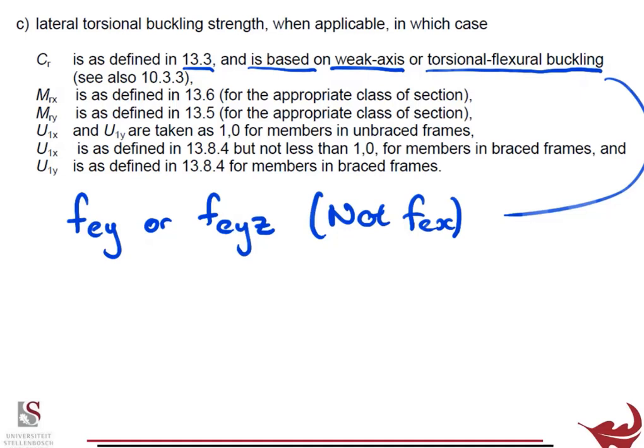Then the moment, this is now a long beam. And what I mean by long is you design it as you normally would. You account for the effective length. If the effective length is 0 meters, then that's fine. If it's a laterally restrained section, fine. Design as a laterally restrained beam. But typically speaking, you now use the KL value that you have.